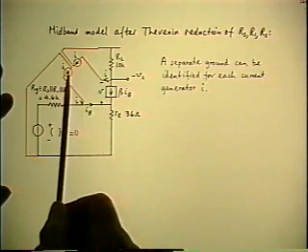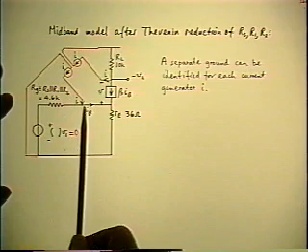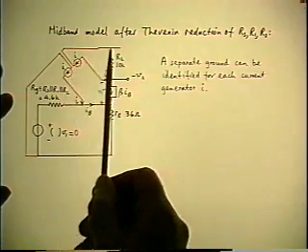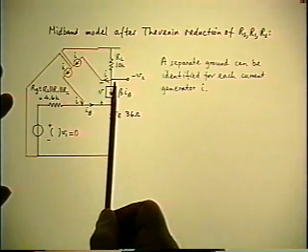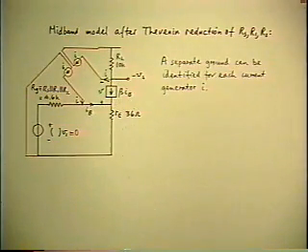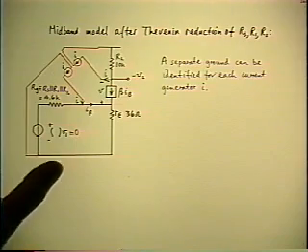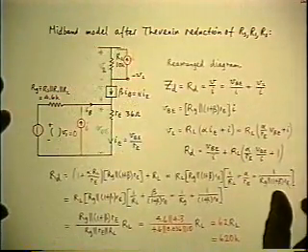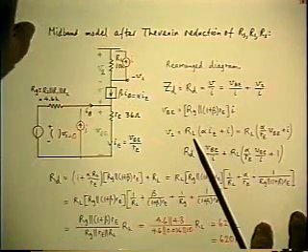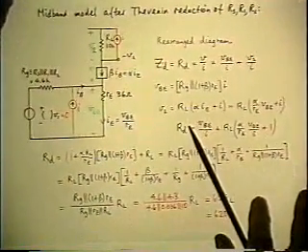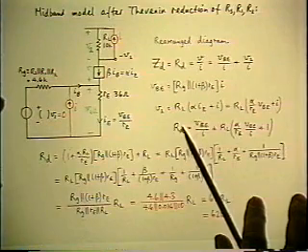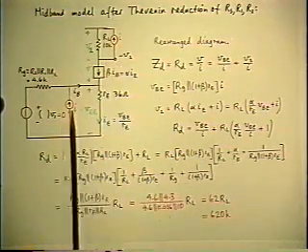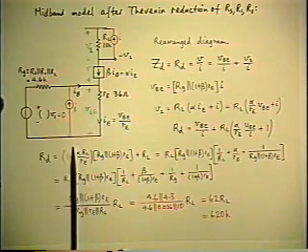But now, you see, this current generator is effectively in parallel between base and ground, and this current generator is effectively in parallel with RL. So without changing the topology at all, I can draw them that way. Here are the two generators placed directly across the relevant nodes.